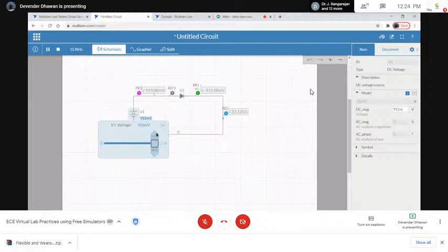Now you see it has increased a lot. From here at this particular point it shot up like anything, like 50 ampere. So this is the knee that we were talking about. So let us just try to plot it. We will plot it on every few readings. Let me just open the sheet.